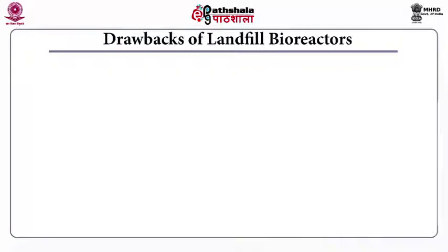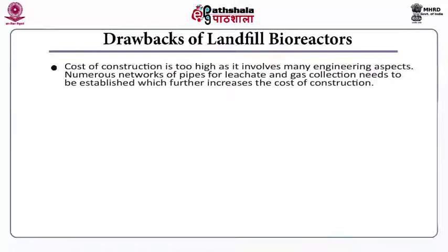Now, what are the drawbacks of the landfill bioreactors? The cost of construction is too high as it involves many engineering aspects. You need a numerous network of pipes for proper leachate and gas collection, which needs to be established properly. Since it involves a lot of waste collection pipes, the cost of construction actually increases, and you require skilled labor for the operation of the LFBR, I mean the landfill bioreactor.